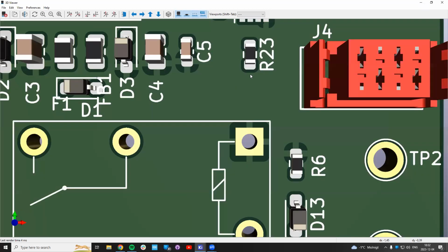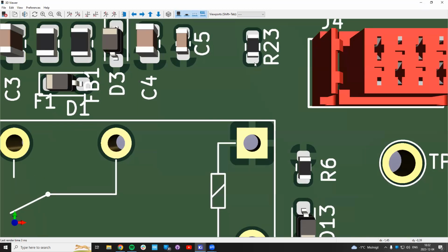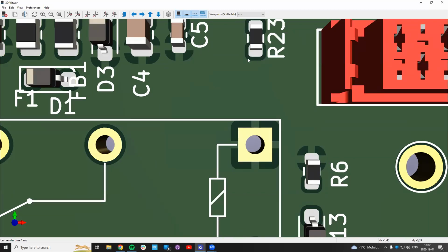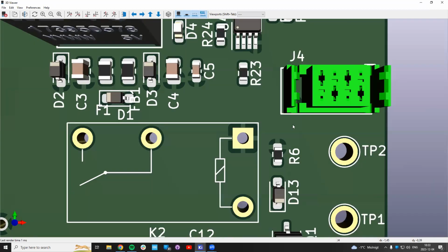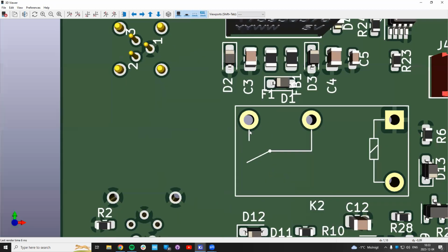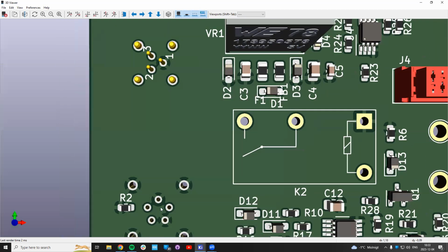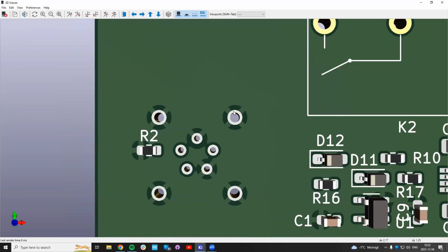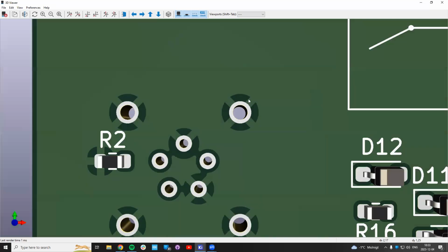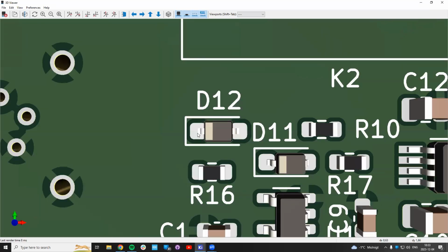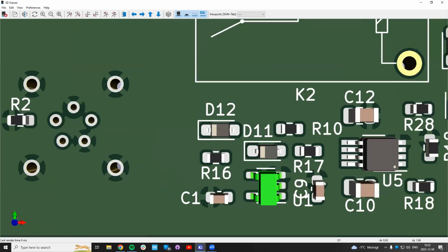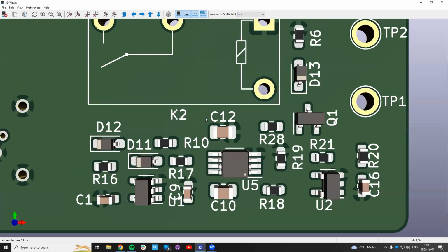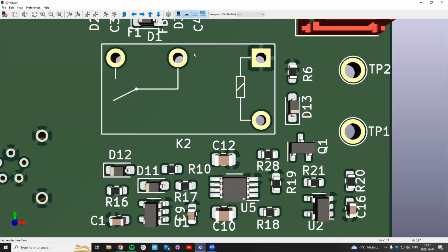And you can see how it is around every pad here. This pad has an electrical net, maybe this is 5 volts, for example. That's why we don't have copper here, because this copper is all ground. So you need to have this cut out so that you don't short 5 volts to ground and such. It's very unintuitive if you haven't seen it before. That's why we have these darker green rings. And these are the holes through all things. This gray thing is exposed copper, exactly as the pads. This is a point you can solder to. Yes, gold as well. Gold is also a point you can solder to.